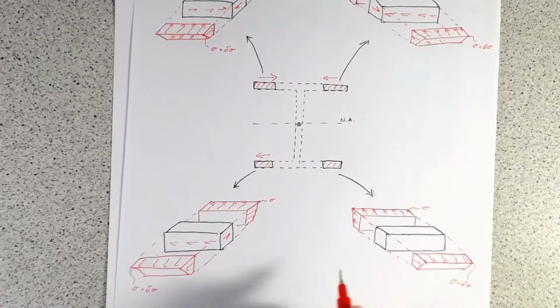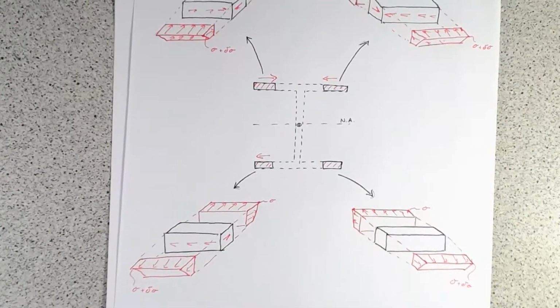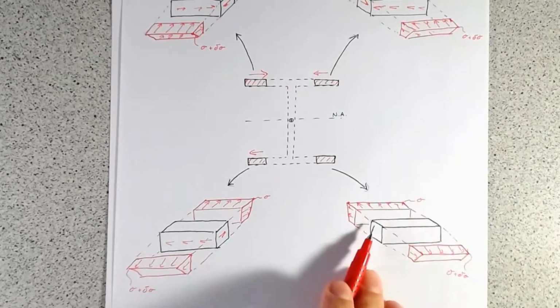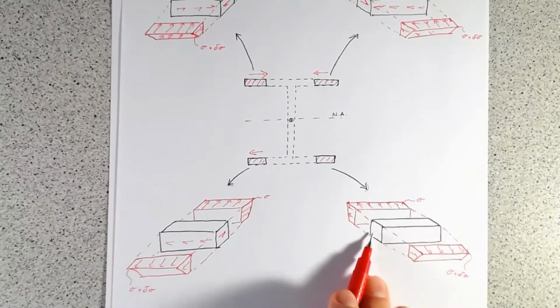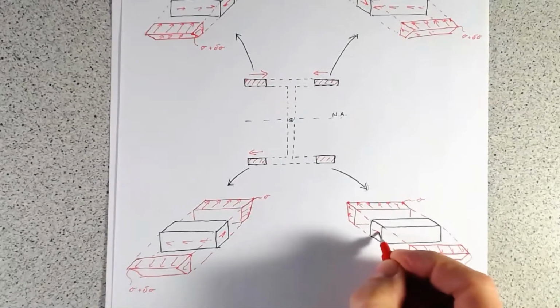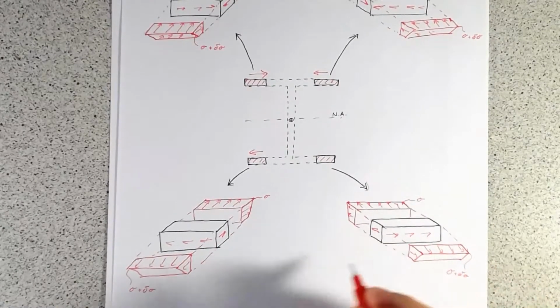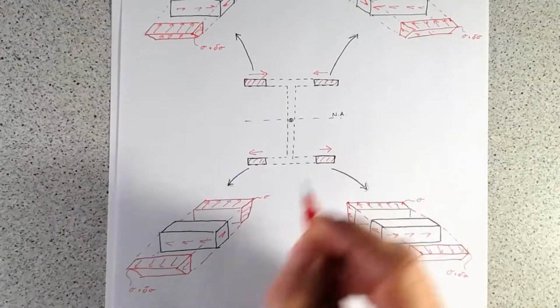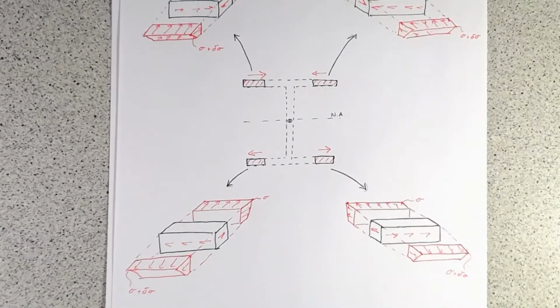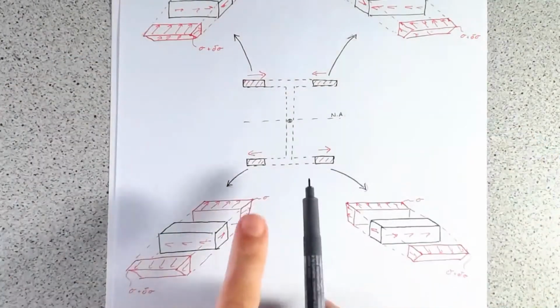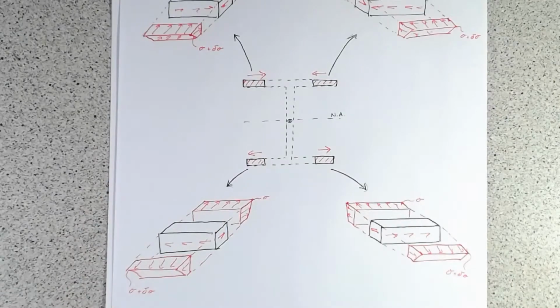And our final side, again, you can kind of see the pattern. We've got more stress over here, so we've got more stress pulling it down this way. That shear stress has to help balance it. It's going to go this direction, and so that means our shear flow points out that way. Now we know the directions for all of them: in compression, they're going towards the web, and then in tension they're going away.